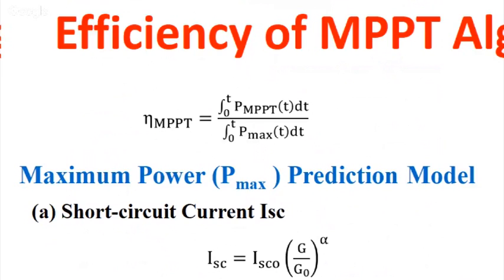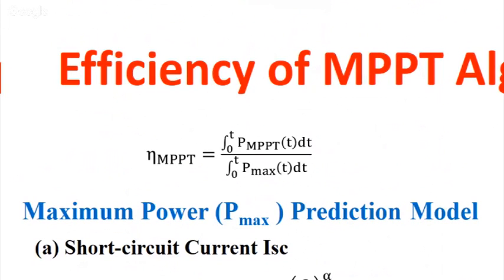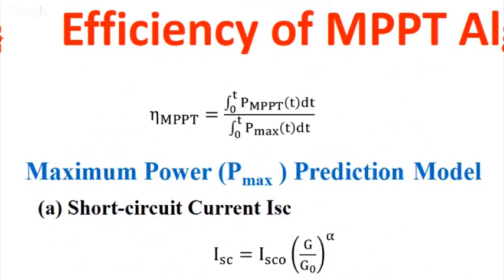So you just take the solar panel, you see what it is. That's why I kept the irradiation meter and the temperature meter there. I took that input in order to measure the efficiency. But when I'm going to give it in real time, that is not required. I can remove this irradiation. Just to find the efficiency of the system, I've used 2 extra sensors. So what I'll do here now, I have to find what is my MPPT efficiency.